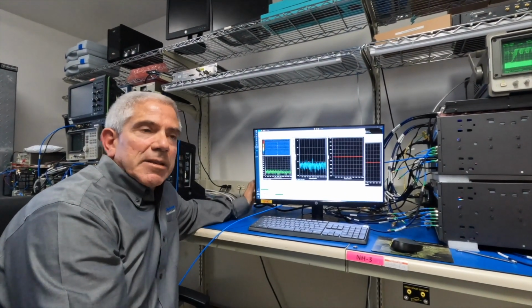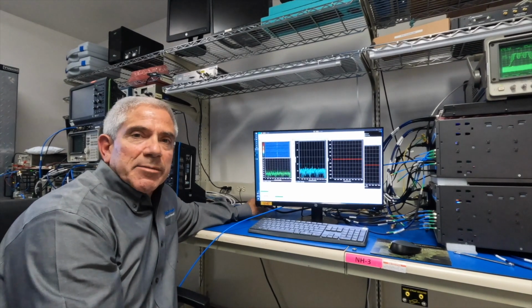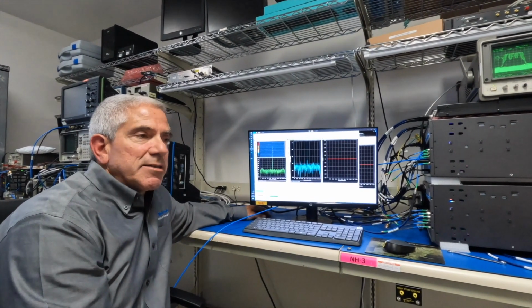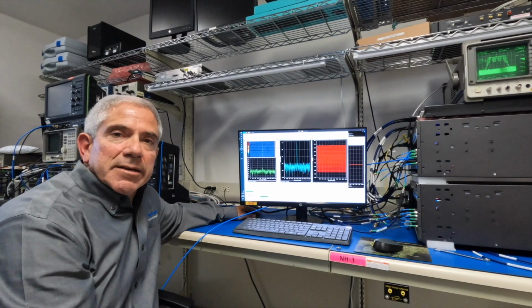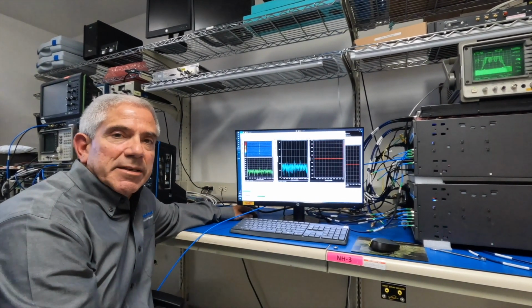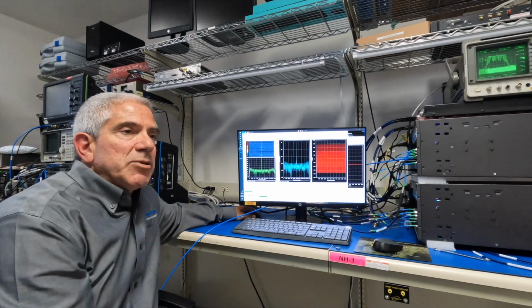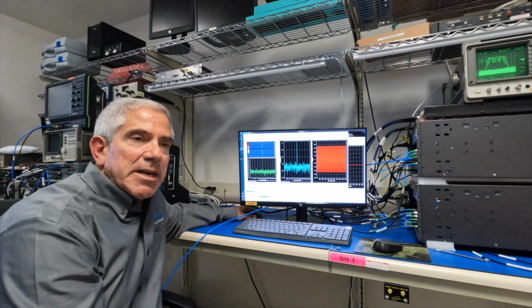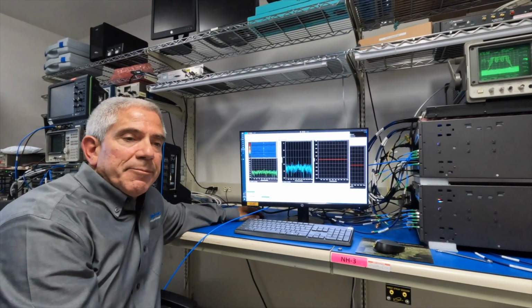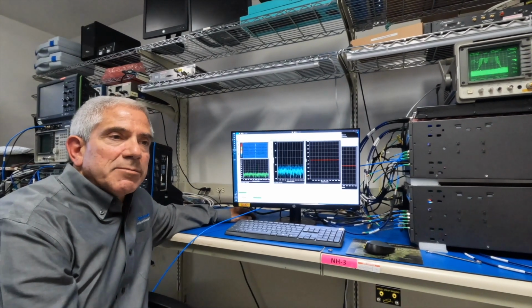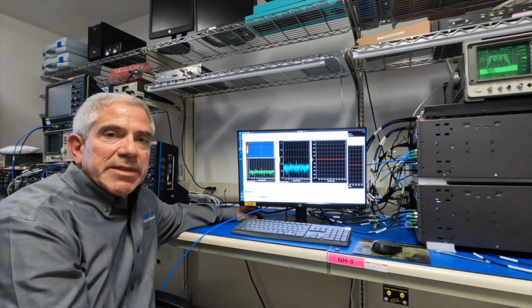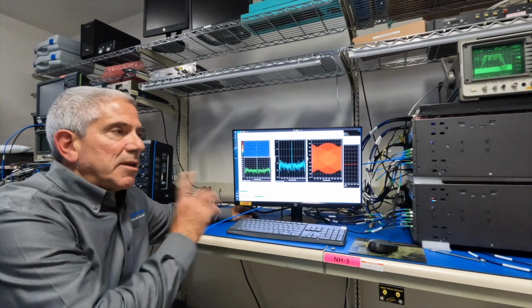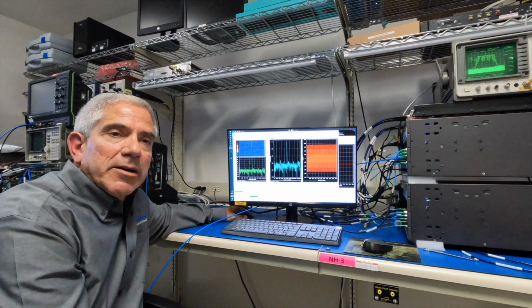So I realized I neglected to tell you about some of the functionality and performance of the CEDAR capture. That particular A to D is actually capable of sampling at 6 gigasamples per second. To be compatible with our system, which has a 1200 megahertz center frequency and some 1200 megahertz LOs going into our RF up converters, we actually use that as a clock reference for the 2400 megahertz and the 4800 megahertz.